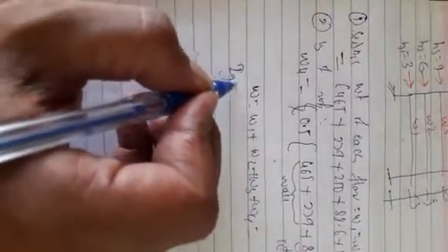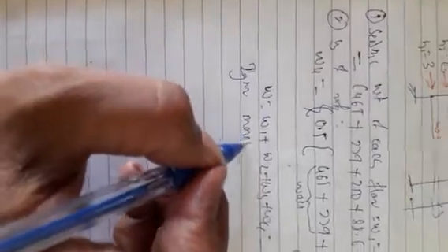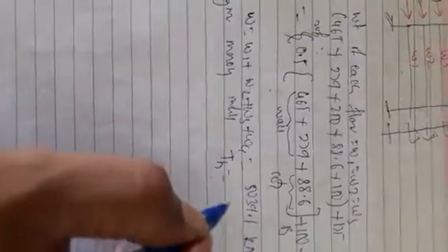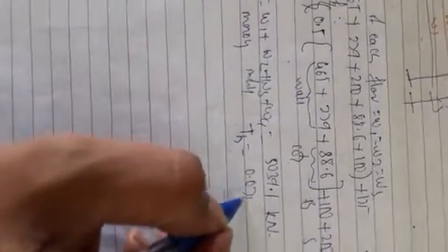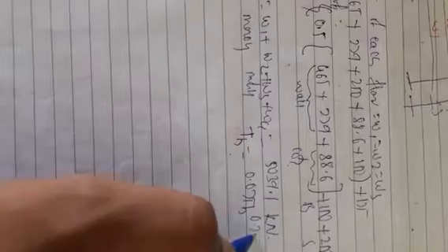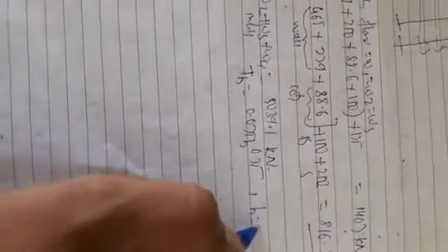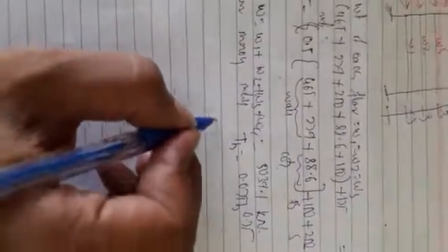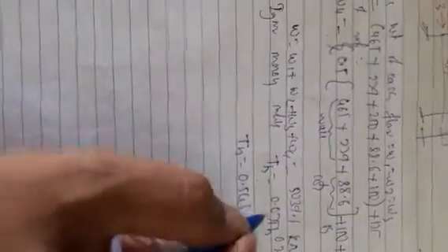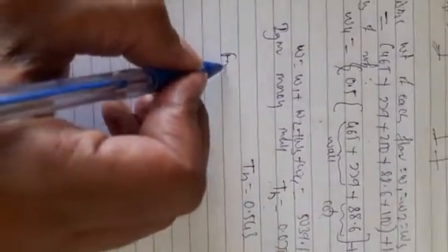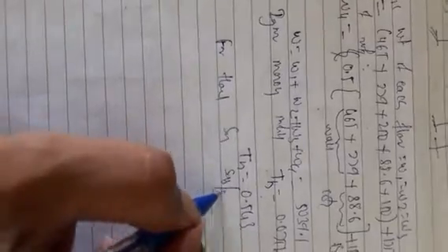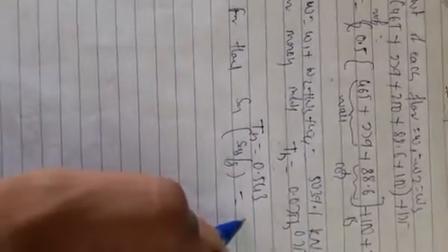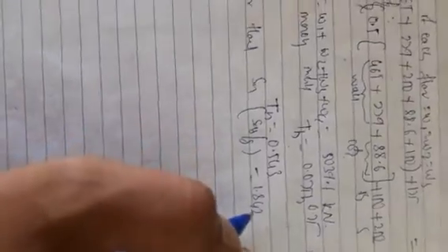Next, we'll start with the AH factor calculation now. Ignore masonry infill. We have natural period Tn is equal to 0.075 h raised to 0.75. Here height h is 12 meters. Therefore, Tn is equal to 0.543. For hard soil, SA by G from the graph I get 1.842.